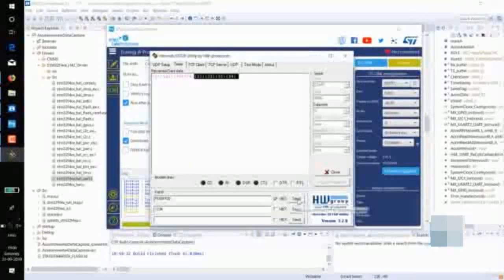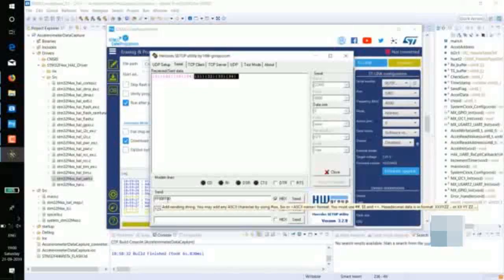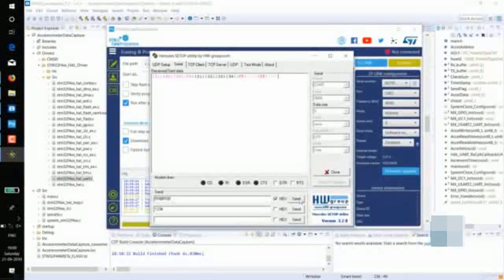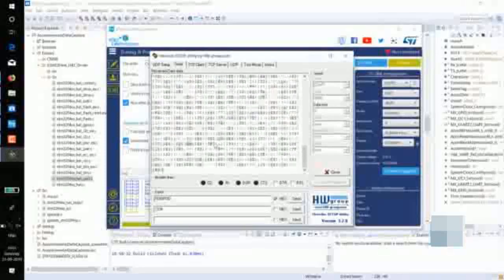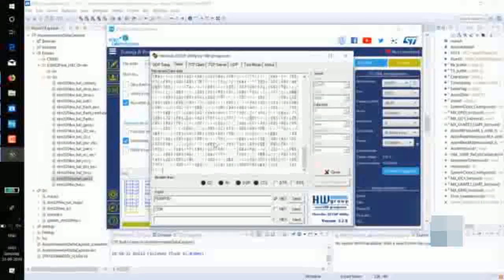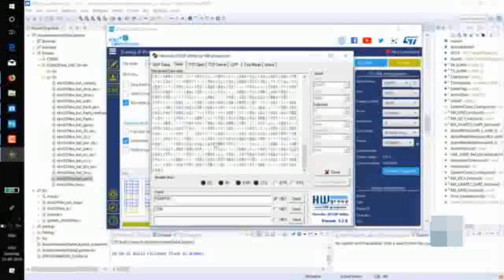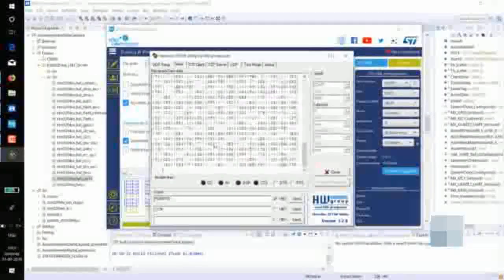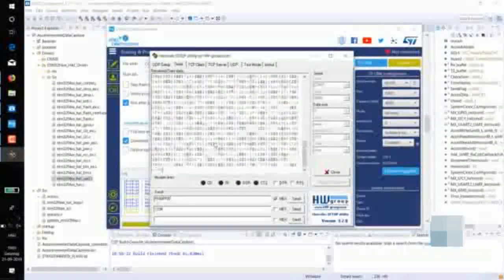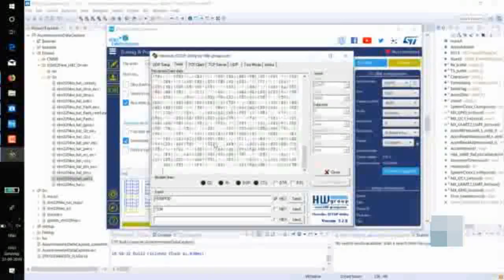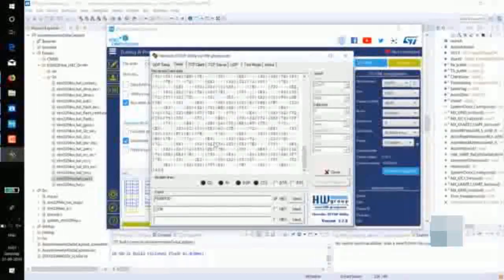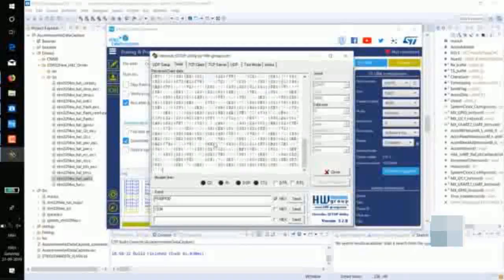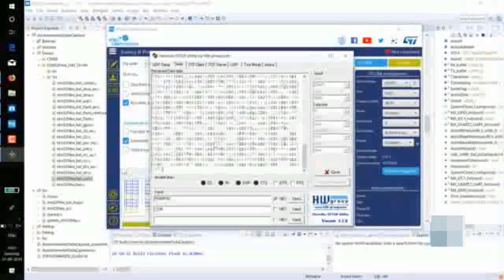Then the next step is to send the confirmation code, which is FF00FF00. Once we send this, a lot of data starts coming from the Nucleo board, which is actually 6 bytes of accelerometer data, 4 bytes of timestamp, and 1 byte of checksum. So we will capture this binary data in the Python script and store it in a file.